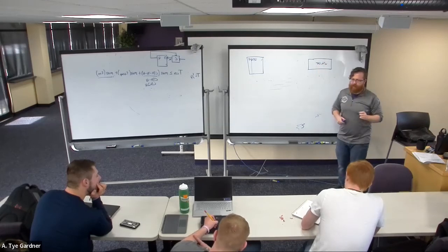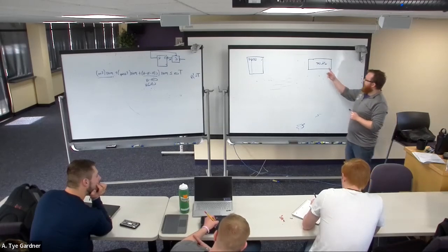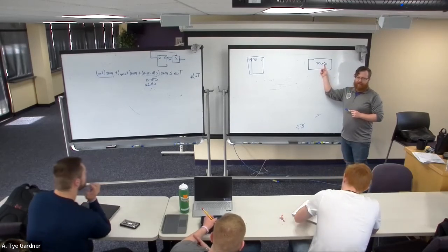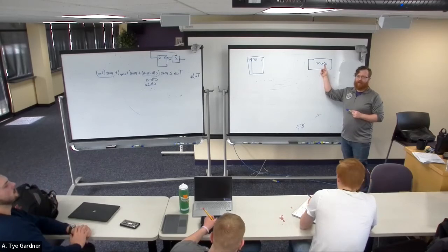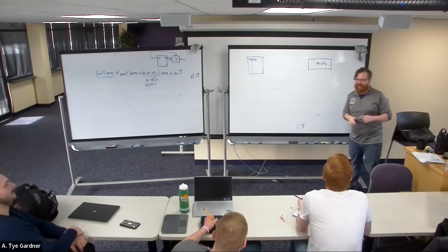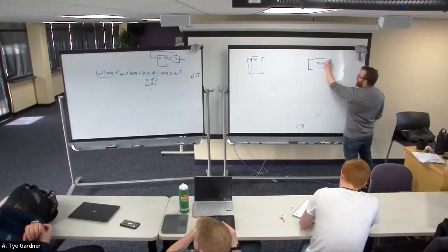I'm going to put a U there for unit 3-bit counter because, as some of you have probably figured out by now, and some of you are about to make that mistake, in VHDL, I'm not allowed to have a number at the beginning of my file names or part names. Why is that the case? It's really annoying, but you're not allowed. It's just how they built it. It's fine. So create your own.